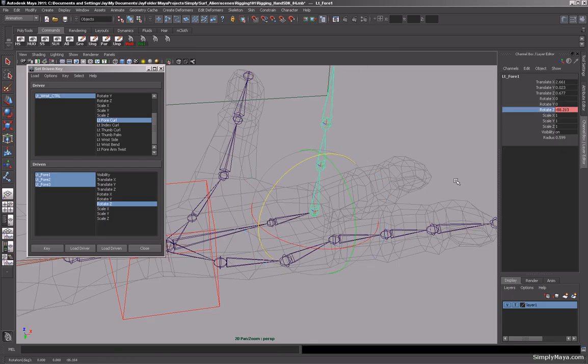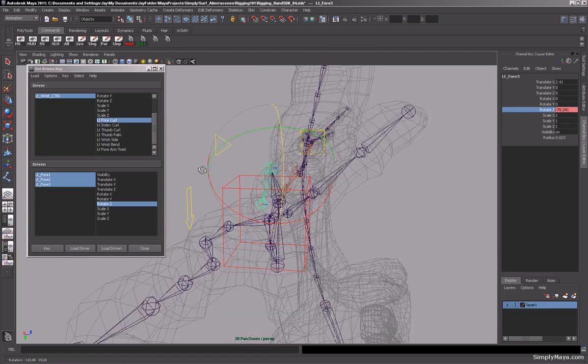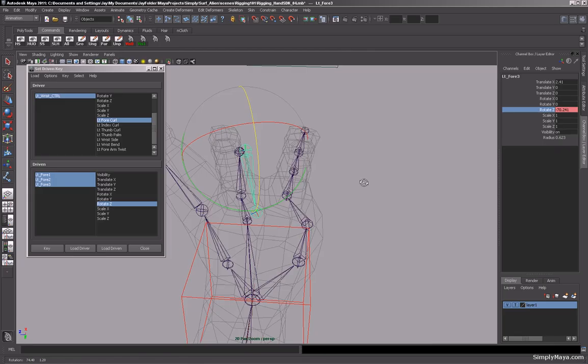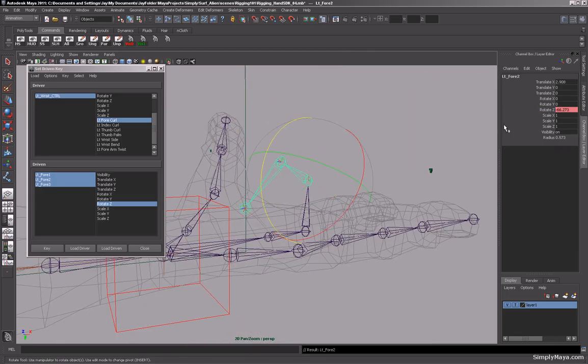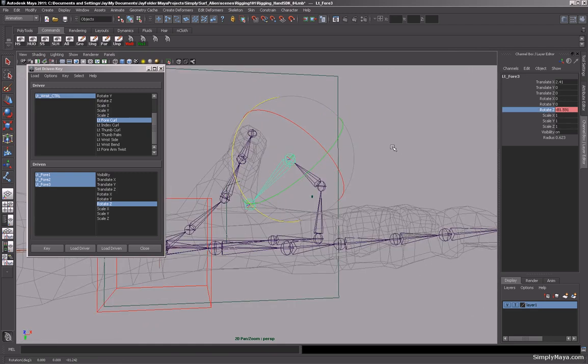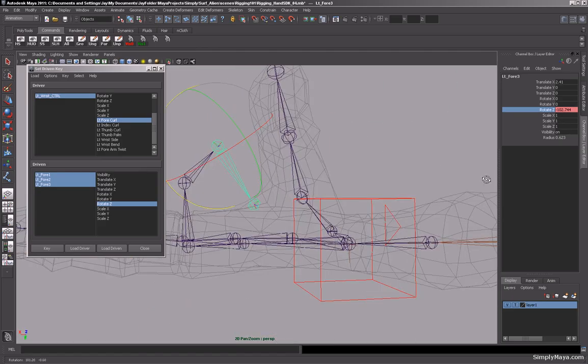So with that done, we can now go in and select the joints once again in our Z rotation axis, and I'm just going to position it using the middle mouse drag. That's all good, and down the center of the joint, and again we can just bring that up and then go back and tweak that ever so slightly back again. So a little bit of back and forth just to get your joints looking right. No big deal, just a bit of patience and you should all be good to go.